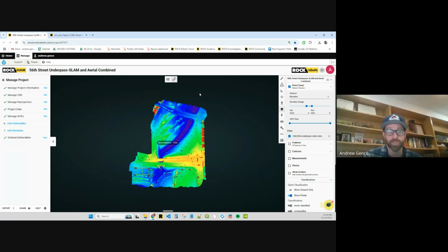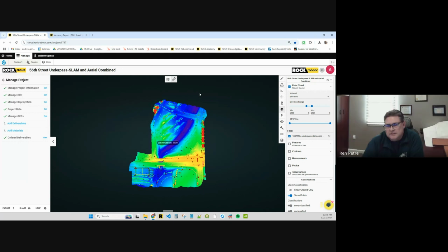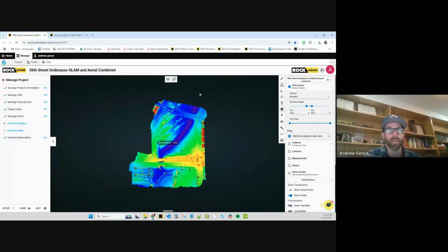For drones specifically? Sure, yes. Keep in mind that your drone and LiDAR are both going to have their own separate GNSS receivers. For your drone, if you want to utilize RTK, by all means go ahead and do it. You just want to make sure that you're able to connect to that source and consistently remain in connection with it.